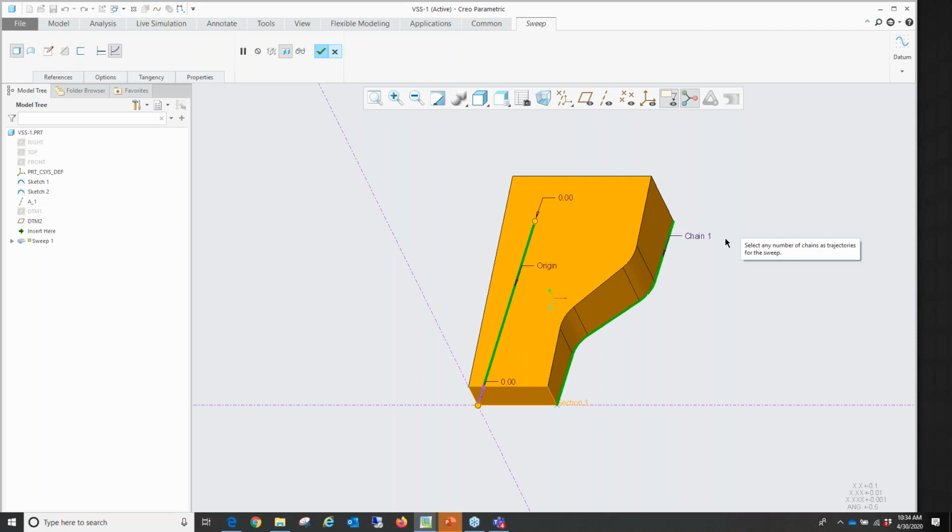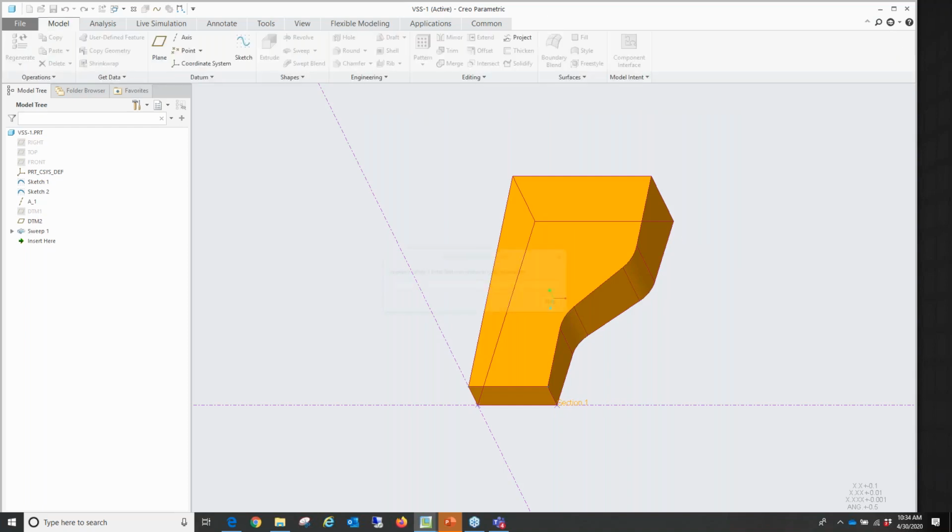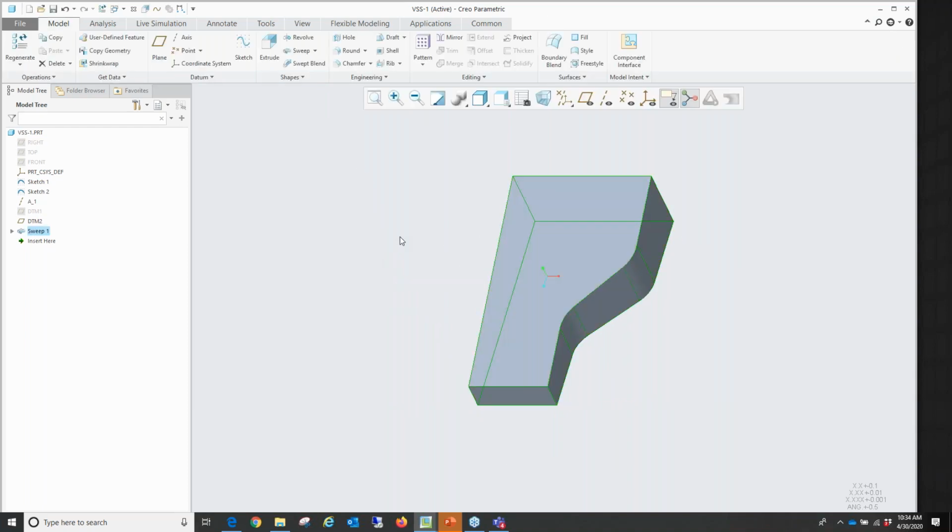Now, let's say I want to have a more substantial change with that dimension. I want to do up and down and stuff. This is where I could also potentially use a graph here. Now, what I'm going to do is I have to make the graph. So I'm going to come over here under my datum dropdown and choose graph. And when I do that, it's now going to ask me for the name of my graph. And again, this can have any name that you want. I'm just going to call it HT for height.